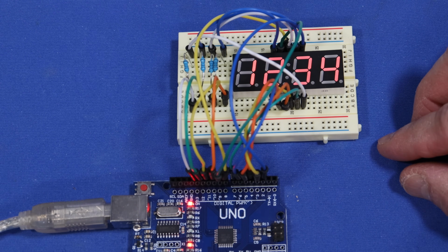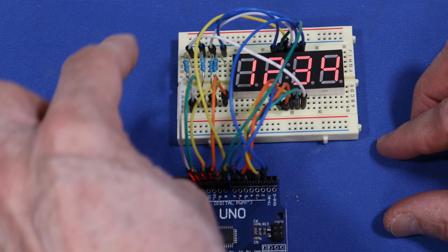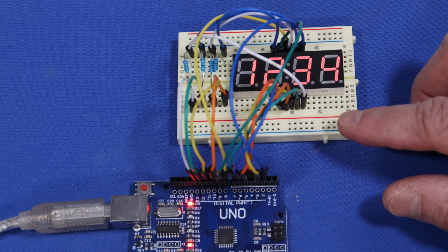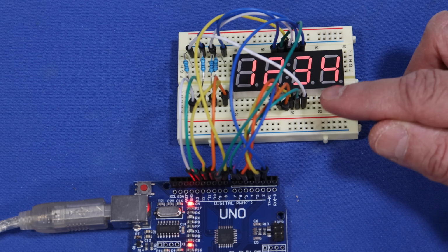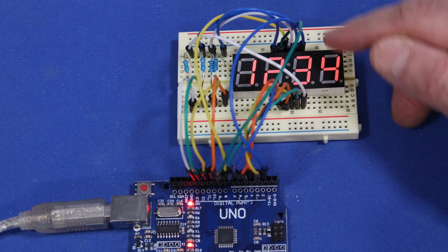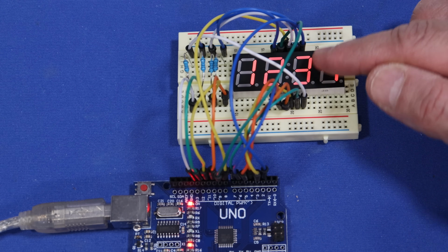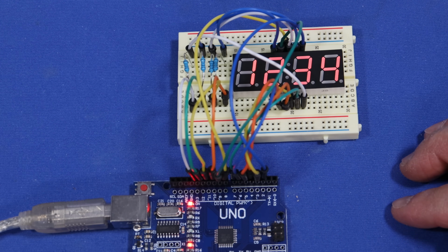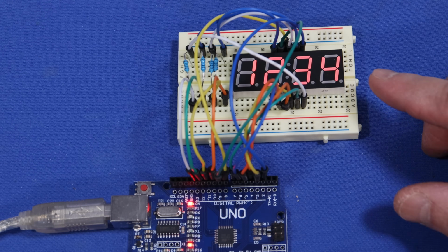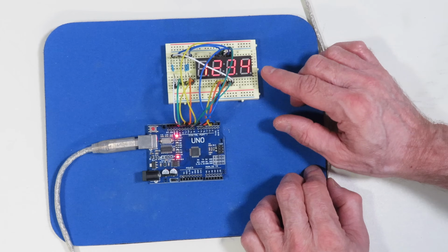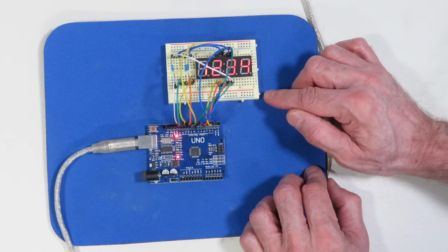So that's one of the consequences of using the resistors on the display select line, as opposed to using 7 or 8 if you include the decimal point resistors on the lines to the individual segments. But otherwise, it's a reasonable compromise. The display is reasonably bright, but not as bright as the individual display was, but it's certainly quite usable.